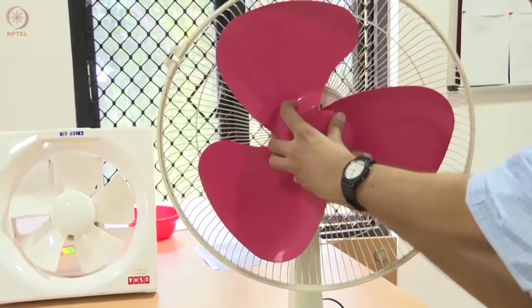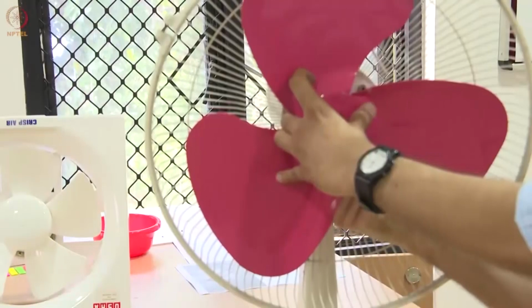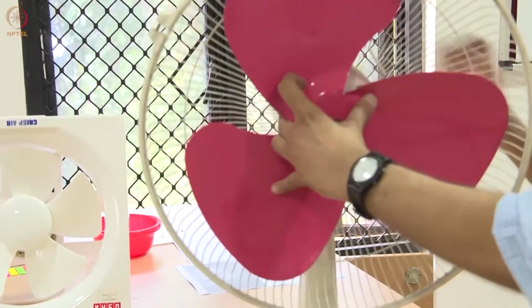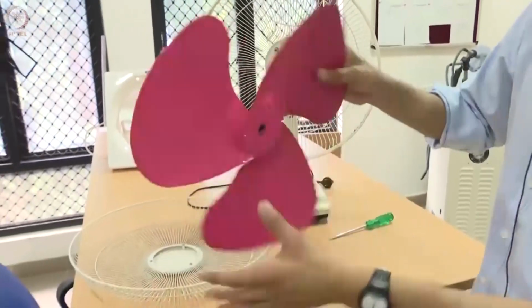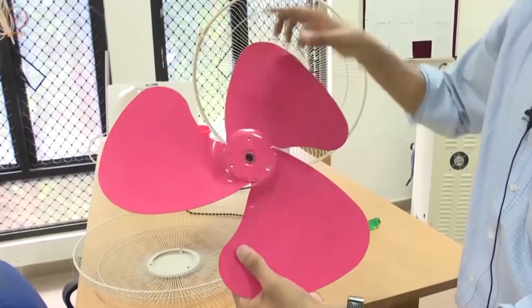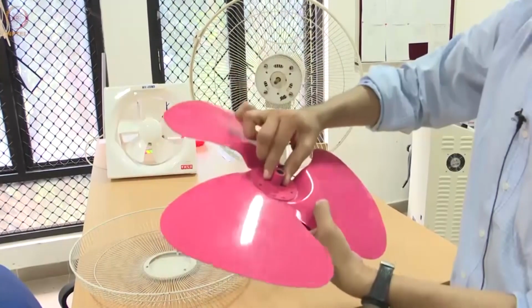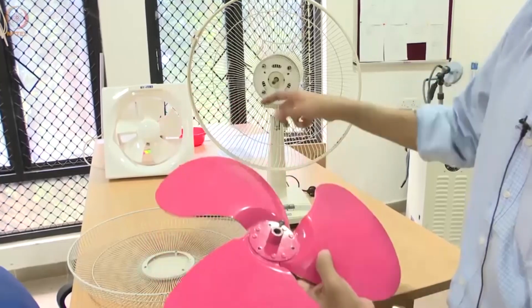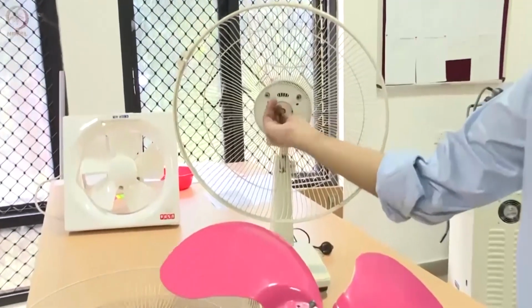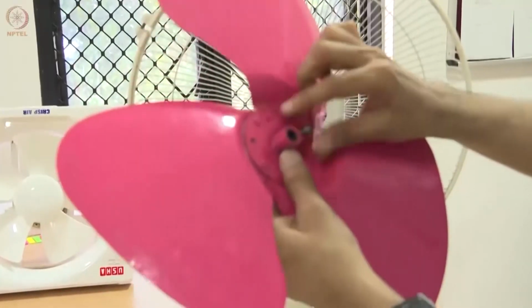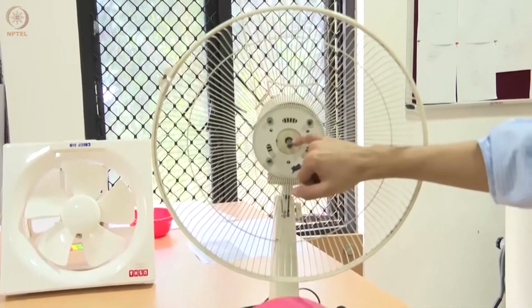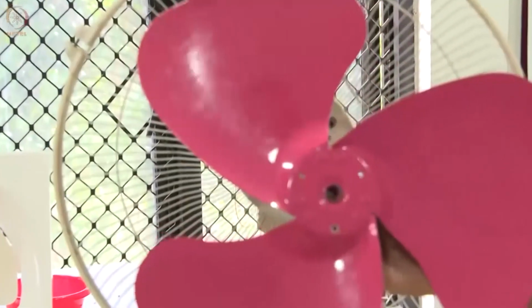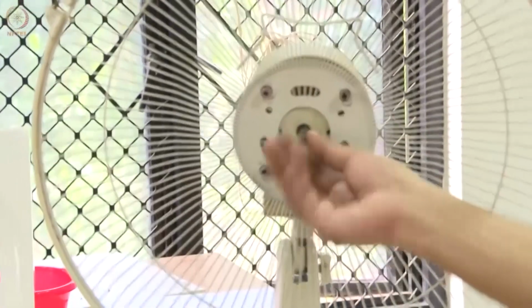Let me first remove the fan blade. I have loosened all the fasteners beforehand just to speed up the disassembly. You can see this is a multi-part assembly, and the components are riveted in place. I have the hub, where this collar engages the motor shaft, and then there is a screw that holds it in place. There is a small dimple, similar to a keyway, that locks the fan in place. That prevents the fan blade and the motor shaft from slipping. So it creates a positive lock.